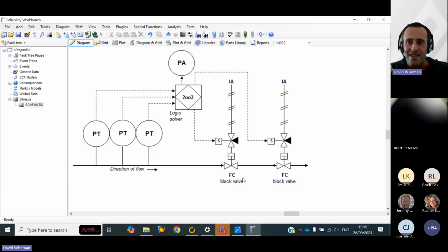People tend to think, when they look at, say, a system, they see maybe 2 things arranged in parallel. Let's say, you've got here sensor, sensor, sensor. They appear to be parallel to each other, so that might make you think, well, AND logic, vote logic. Parallel means AND. Conversely, series means OR.